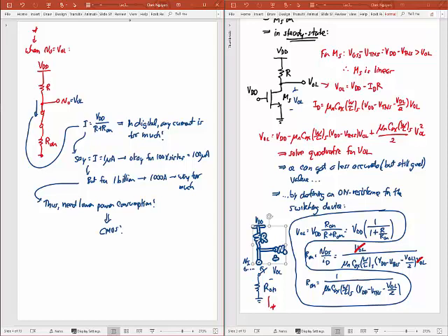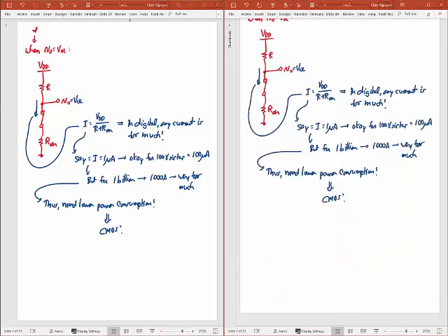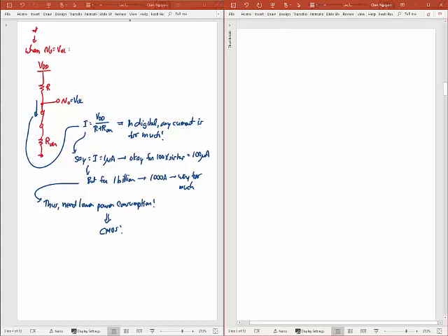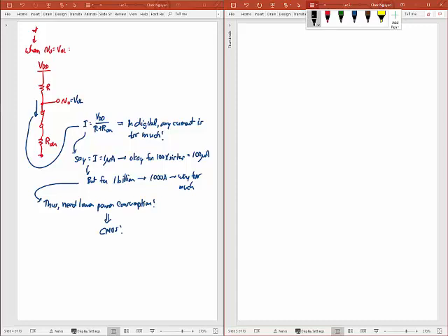And so they did that for a while, but when you do that, you still get that power consumption. And so the way to eliminate that power consumption is to use a complementary device, and that's where CMOS comes in. C stands for complementary in the word CMOS. And so we should talk about the CMOS inverter.